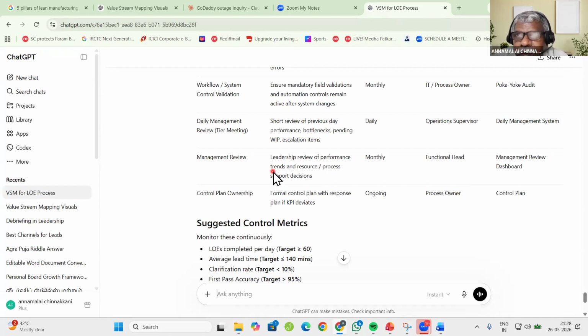Then you identify which is the one which is contributing more. So that you identify as the choke point, and then try to split that choke point, try to focus only on that. Try to understand what is the problem, why the choke point, why the output is lower there, whether the productivity is the issue, or the maintenance of the running time is the issue, or the changeover time is the issue, or the quality rework is the issue, or something like that. Try to identify what is the real issue in that choke point process, and then take action. Depending upon the problem, you take action.